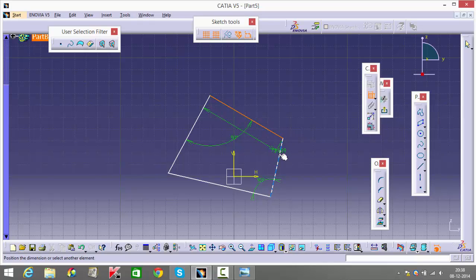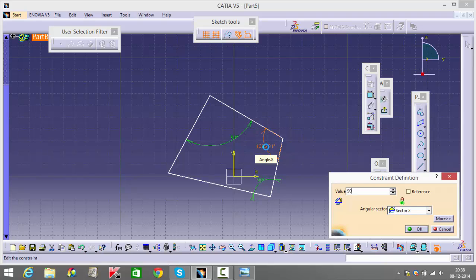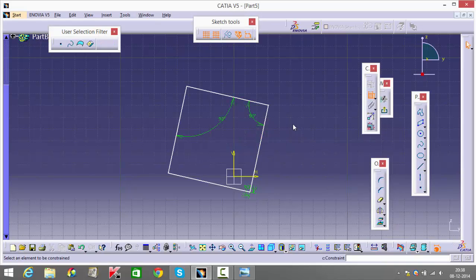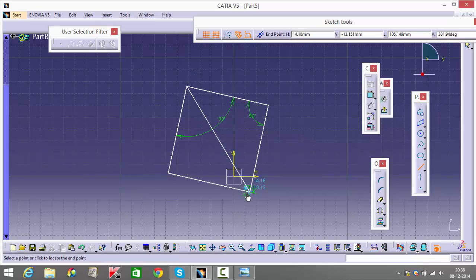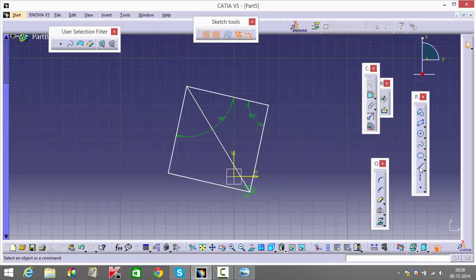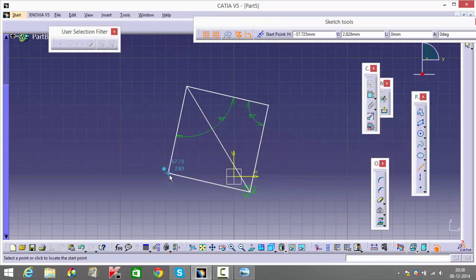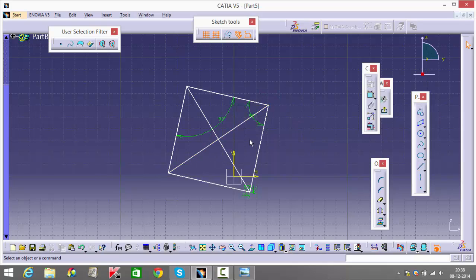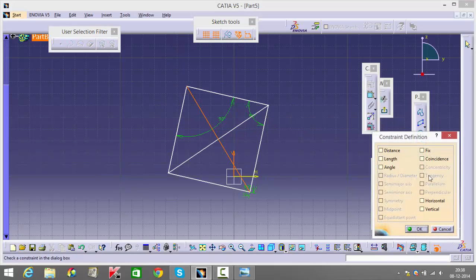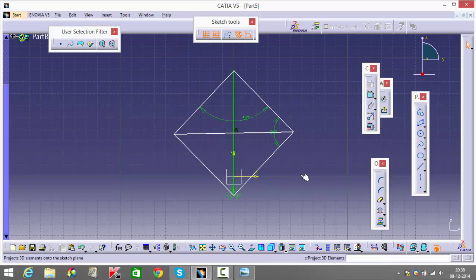Okay, it actually would have been a good idea to keep at least one of those parallel kind of constraints. Okay, delete. So what I'm now gonna do is I'm just gonna draw diagonals. Okay, now I'm gonna select this and select this surface and make this coincident.